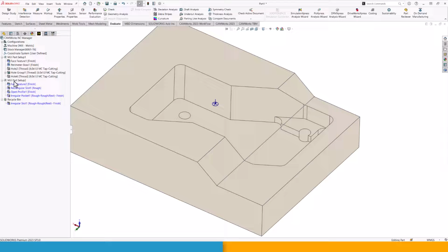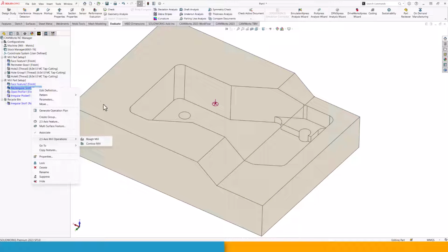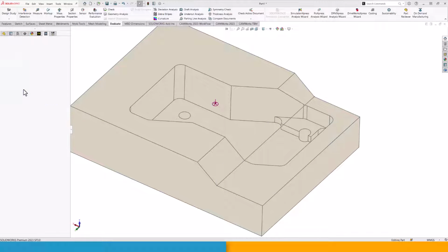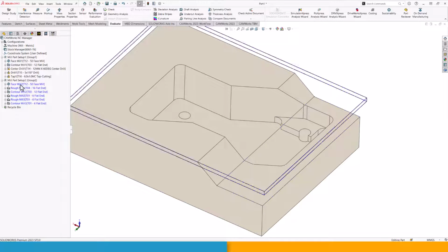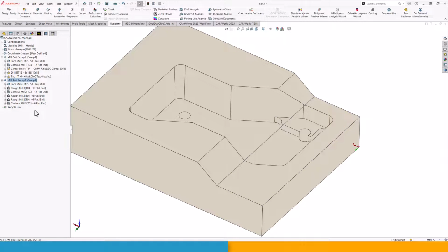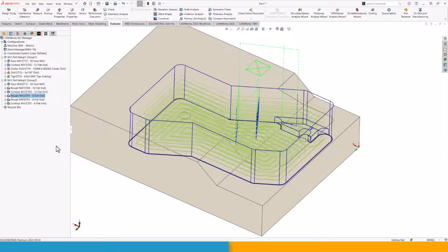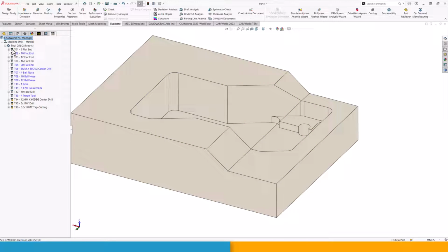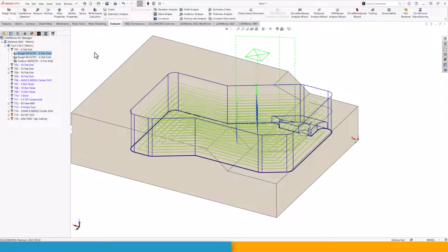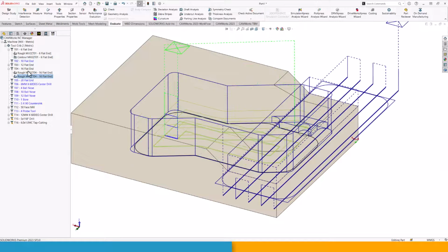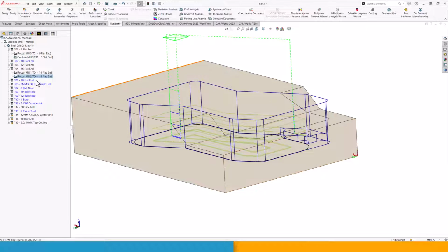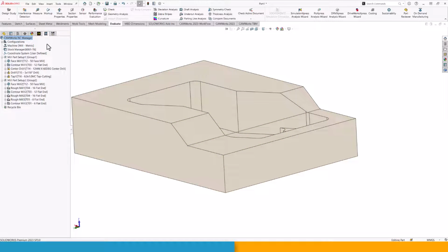Now at this point, we can go one by one, right click, and then insert rough mill contour and so on. But in fact, I'm not going to do too much for this. I'm just going to run the strategies from the TechDB, then generate the toolpath, and then have a look. I can see that I have a rough mill with a 6mm tool, and that is definitely not what we want. So let me go in here, find this rough mill, and maybe move that to my 16mm flat end. It's going to update the toolpath very quickly, and I also want to make sure that we machine the top face over here. So let's just go back to the rough mill,